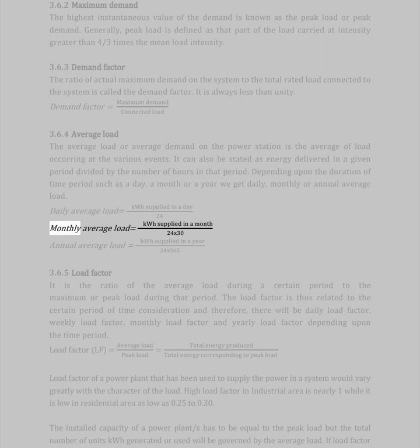Daily average load equals monthly average load equals annual average load. 3.6.5 Load factor. It is the ratio of the average load during a certain period to the maximum or peak load during that period. The load factor is thus related to the time period under consideration, and therefore there will be daily load factor, weekly load factor, monthly load factor and yearly load factor depending upon the time period.